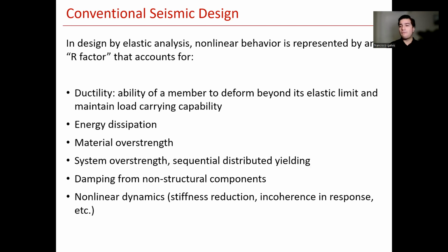So these are factors of that compromise, where we will allow some nonlinear response, which basically means we will allow damage in the building, such that the cost of construction is lower, and then we still keep that life safety performance objective.